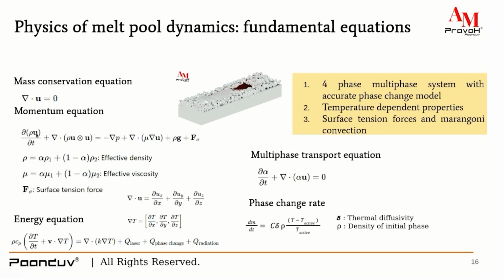Now, in the momentum equation, first of all, why will the momentum equation come? Do we have fluid here? Yes, of course. First, the fluid that is the molten metal that is formed due to the heat source provided by the laser. That is the first fluid.